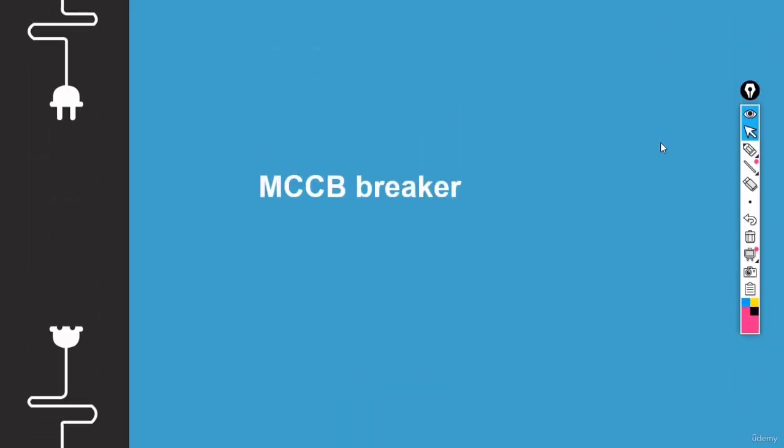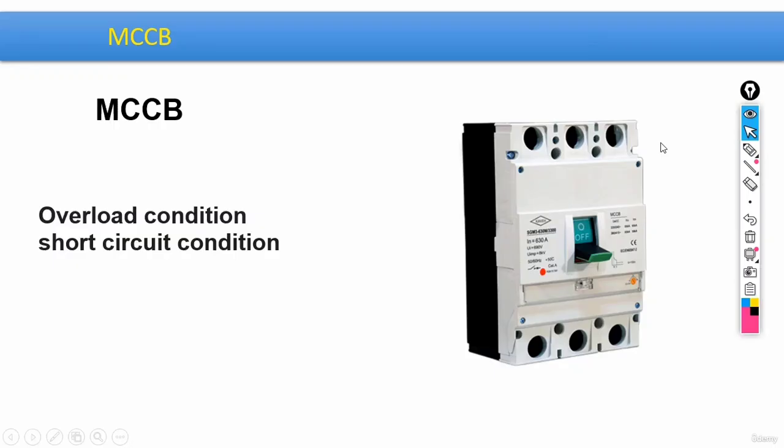Welcome back, guys. Let's talk about another breaker. This one is called MCCB. I mean, the last one was MCB, this one is MCCB, so pay attention, don't get confused. To be honest, they work kind of the same, but the difference is that the MCCB breaker supports a very high electrical current. And compared to MCB breakers, this one has some additional sub-items, you can say. As for the similarities with MCB, this one also protects the circuits against overloading and short circuits.